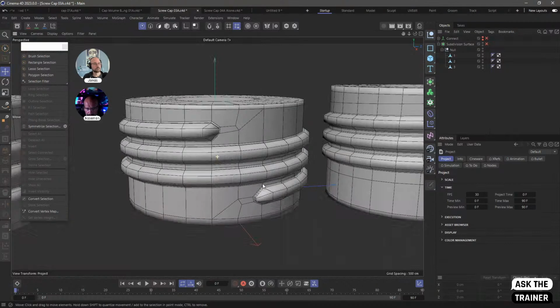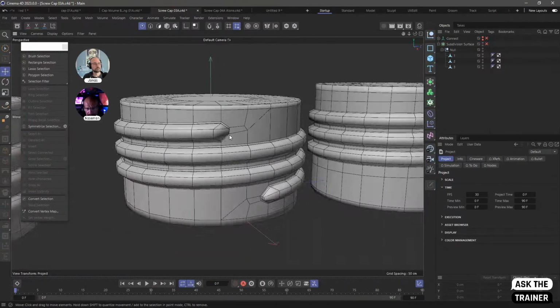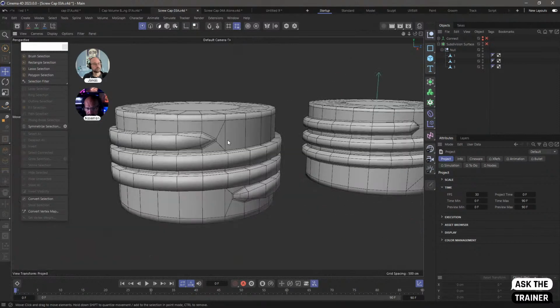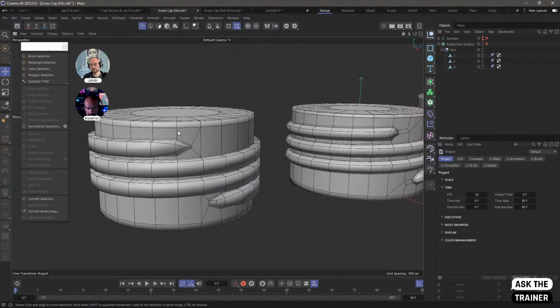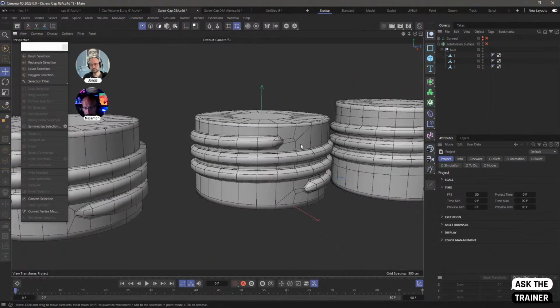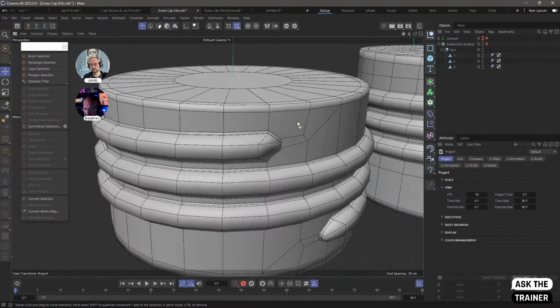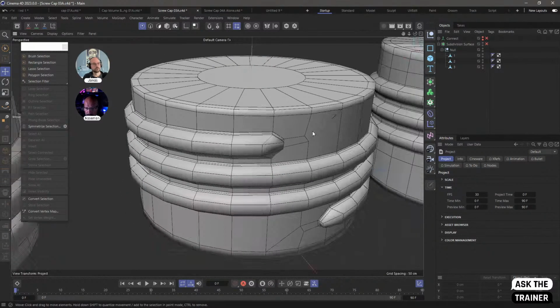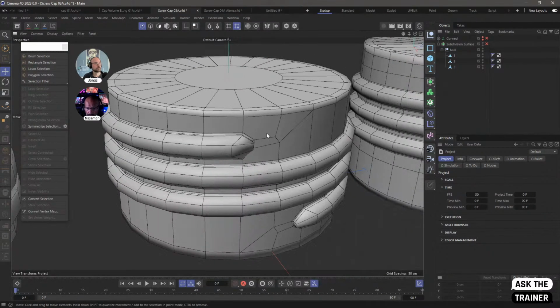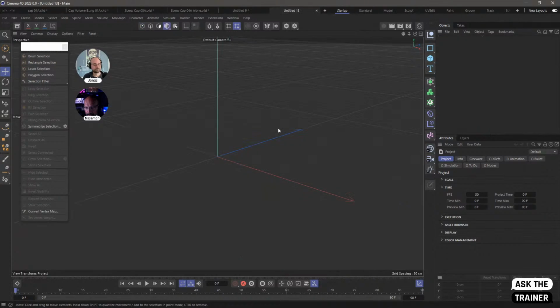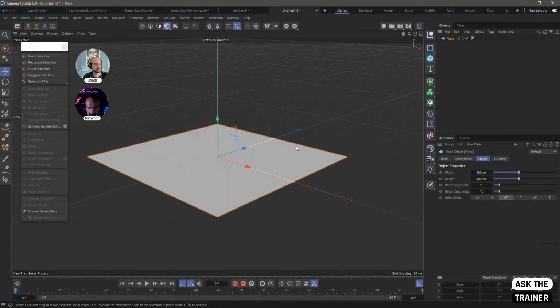They have these n-gons. Now, Cinema 4D handles n-gons in subdivision surfaces pretty well. So if you're staying in Cinema 4D or any software that supports n-gons, you're good to go. But there are times when you definitely need to work with quads, so you need a different configuration. We're going to do this model in a quick bit. When it comes to n-gons and subdivision surface support, and that applies to triangles as well, as long as the transition from a quad to a triangle happens where there's no curvature, you shouldn't have any artifacts. That is something you need to remember overall.